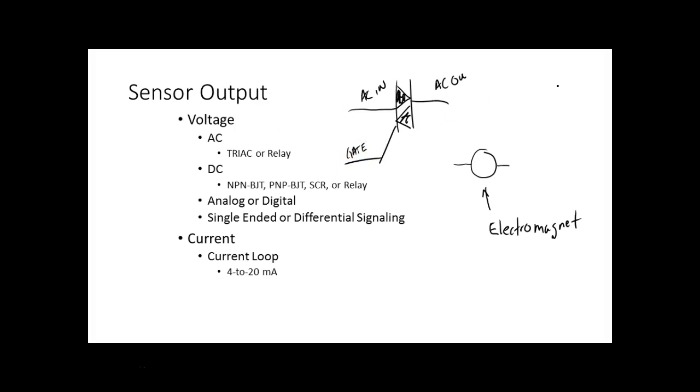So it simulates a relay contact, right? You understand? But we don't have a coil. It's solid state. So we use these all over the place. I got lights at my house, motion detectors. When I walk outside, they come on. Well, there's no relays in that. It's got a triac. It's a solid state relay. You can buy solid state relays. That's what they're called. And they'll have two coil inputs, but they're not really inputs. They're just nothing but firing this triac.